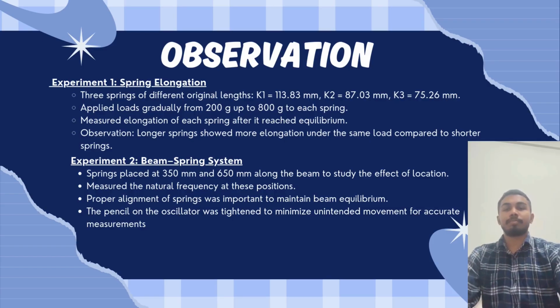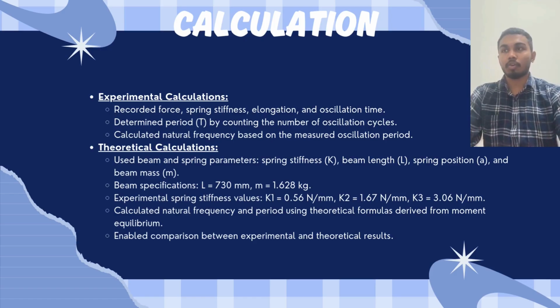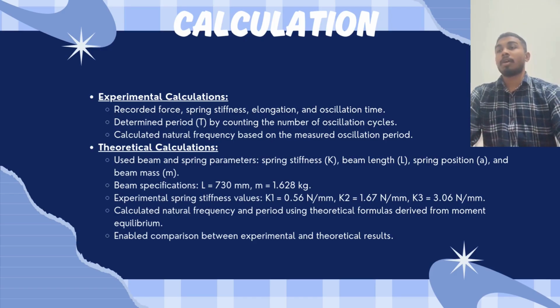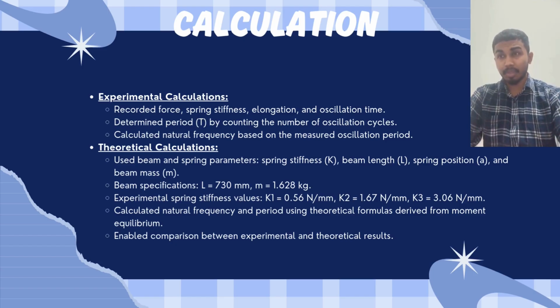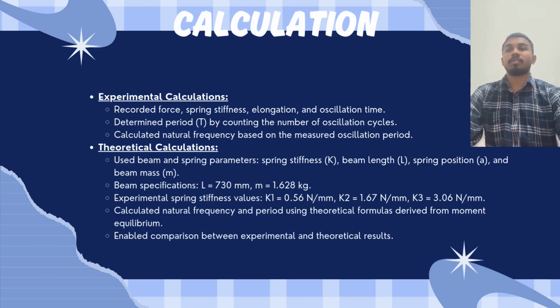Now I would like to talk about the calculation we obtained from this experiment. For experimental calculation, we measured force, elongation, spring stiffness, and the oscillation time. By counting the number of oscillation cycles, we determined the period, which allowed us to calculate the natural frequencies of the system.